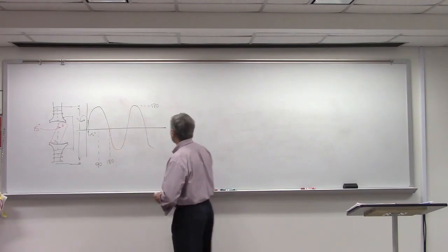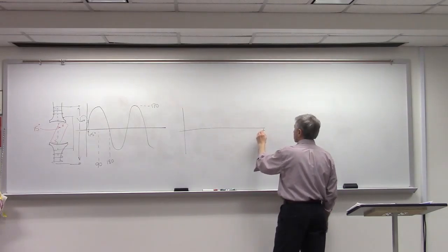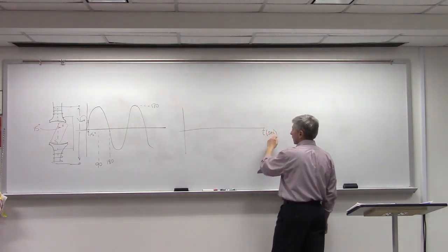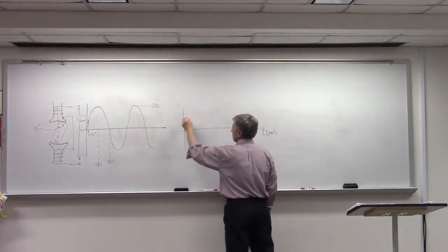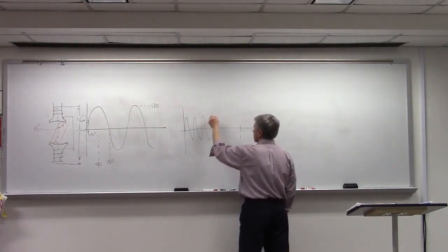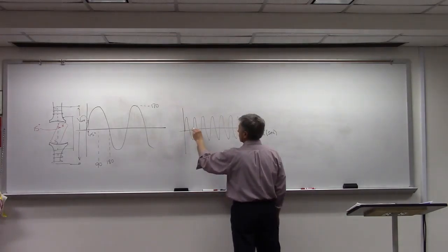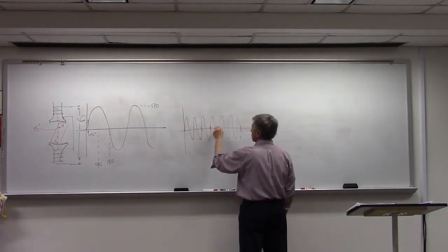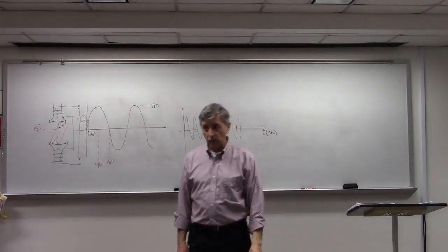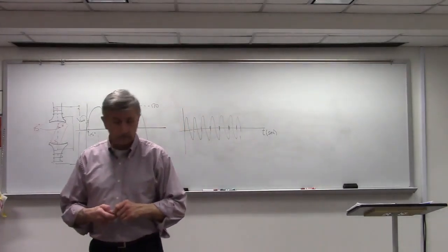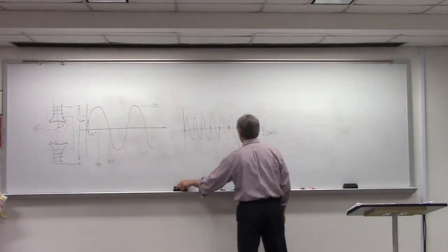So if we have an x-axis that's measured in seconds, and we've got 1 second here, and this guy's doing this, we have 1 cycle, 2, 3, 4, 5, 6, 6.5. So that frequency would be 6.5 cycles per second. I want to make it even, I'll put one right here. So there's 6 cycles per second.